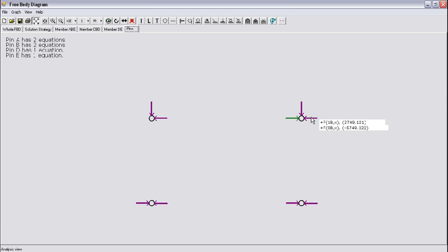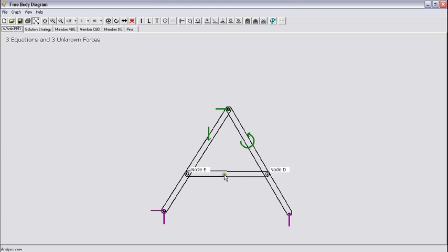So in the x direction, it's no longer a straightforward application of Newton's third law. I call situations like this special pins, where more than two things are happening. So at node B or pin B, more than two things are happening. That is, there is a member, a second member, and the third item is a horizontal force.